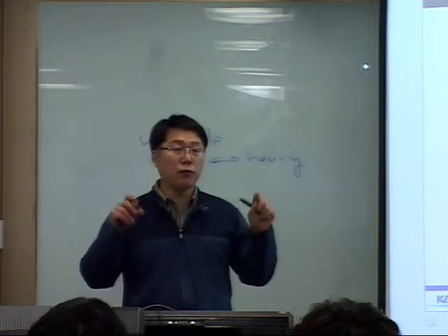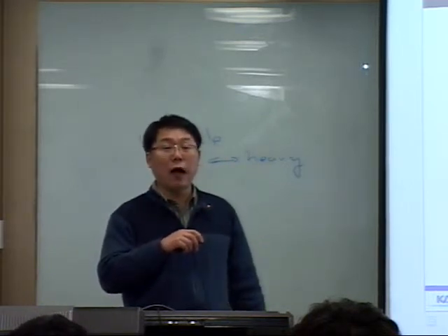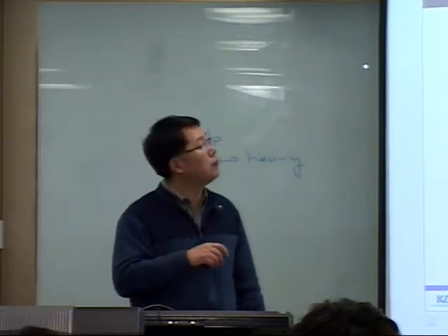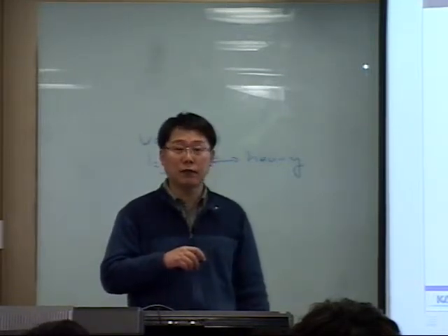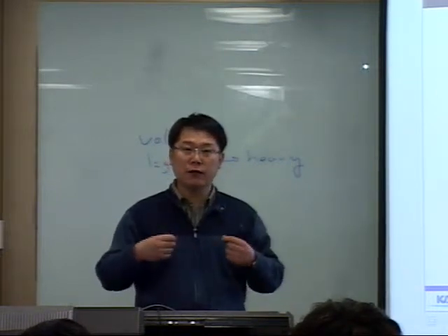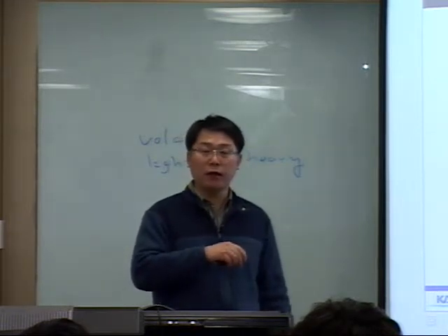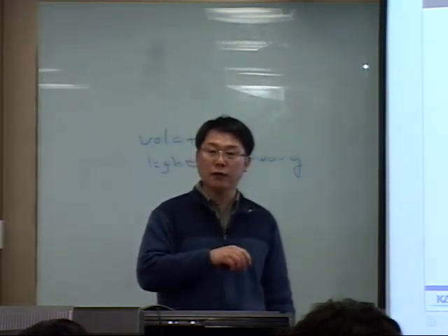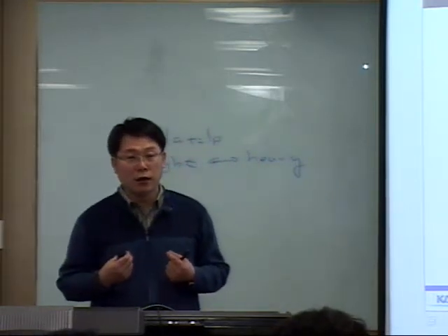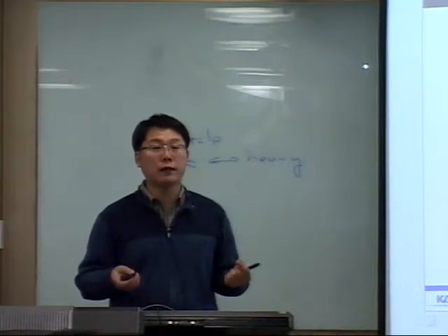Then we put LNG into this hot tank. Minus 19 is hot compared to minus 160, right? So the hot wall will generate some heat ingress into the cargo tank, into the cargo LNG. That means we can get more BOG than the normal case.